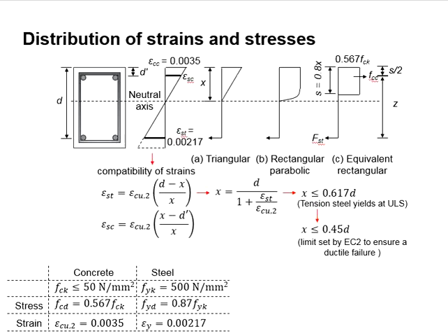When the member is subjected to low loads, little deformations develop. This leads to very little compressive strain of the concrete and small x here, which results in a small stress block to provide the compressive force. Now, reaching the ultimate state, just before the concrete fails, the maximum allowable compressive strain of the concrete is 0.0035. This is set by Eurocode.